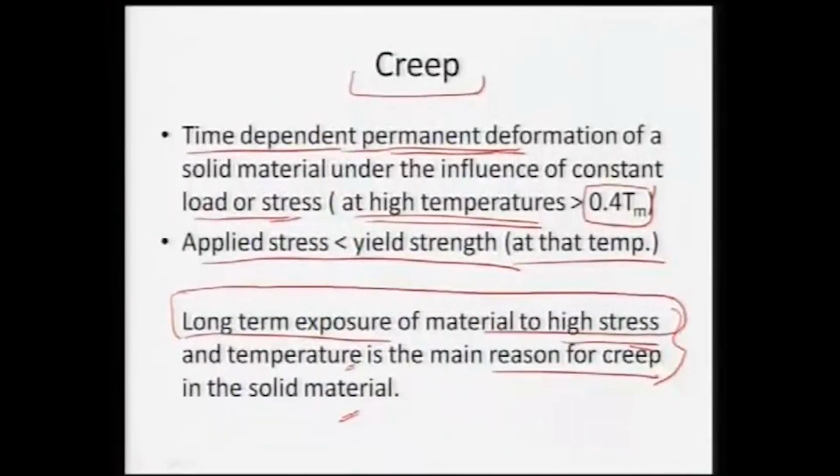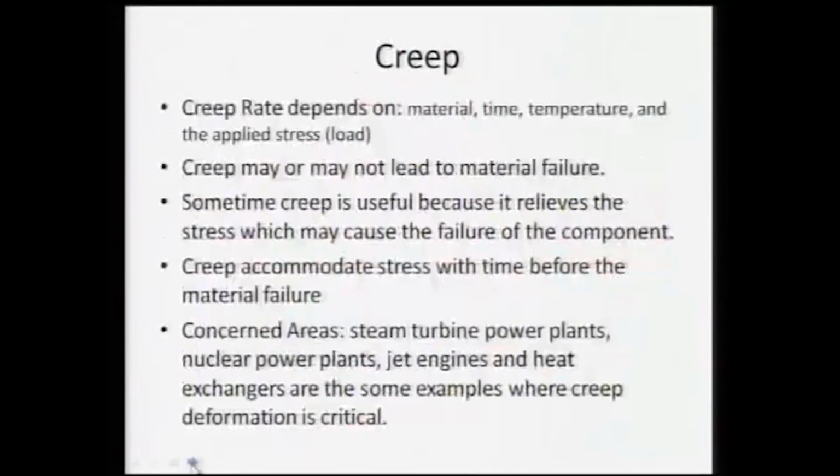So, in that case we can see that the creep also needs to be controlled by enhancing its strength. So, we can utilize again certain design criteria, and we can avoid long term exposure of the material to high stress and temperature to avoid the creep. And again the creep rate will depend on the kind of material we have. So, if we have a very high strength material, the creep will be delayed, the time of exposure. So, if we expose the material for a long enough time, the creep deformation will be pretty high.